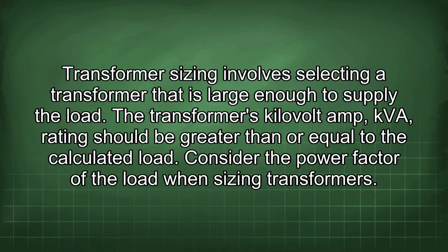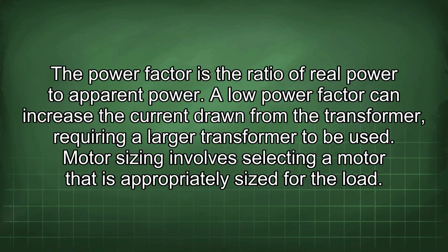Transformer sizing involves selecting a transformer that is large enough to supply the load. The transformer's kilovolt-amp (kVA) rating should be greater than or equal to the calculated load. Consider the power factor of the load when sizing transformers. The power factor is the ratio of real power to apparent power. A low power factor can increase the current drawn from the transformer, requiring a larger transformer to be used.